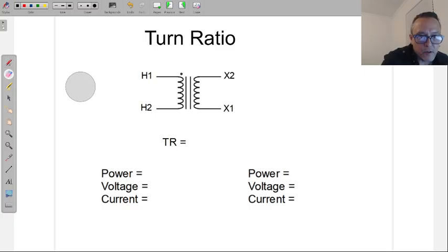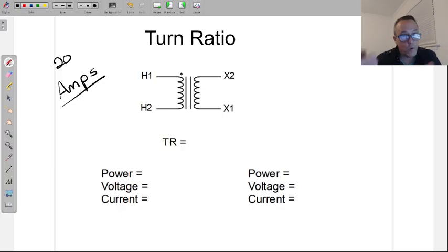For example, for those of you who've talked more about breakers, when you go to select a breaker, you're not selecting a breaker based off of what you are wiring up's wattage or VA. You are selecting the breaker based off of what you're wiring up's amperage. So a breaker is rated for, let's say, 20 amps, not wattage. Whereas a transformer is based off of the wattage of what it's going to be powering up.